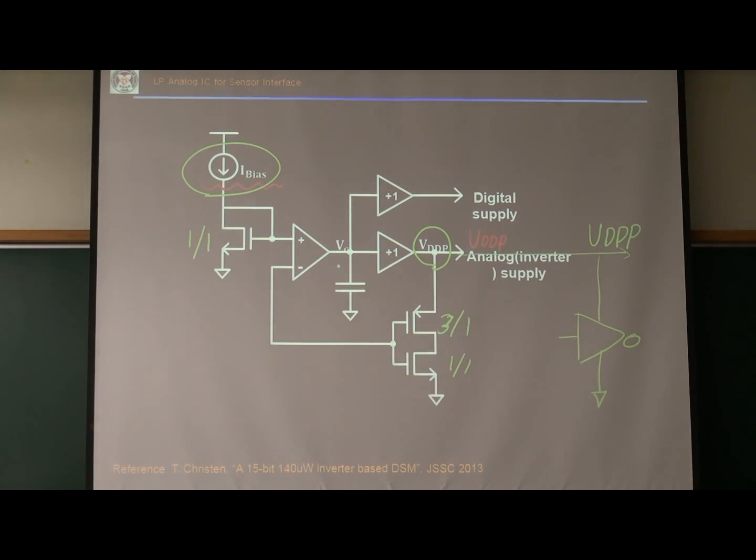Then the situation is the same as this inverter operating at the logic threshold point. At the logic threshold, the input voltage is the same as the output voltage. So the situation is here: gate voltage is the same as drain voltage. So if I make this voltage, say V1, the same as that voltage there, by using this negative feedback loop here...